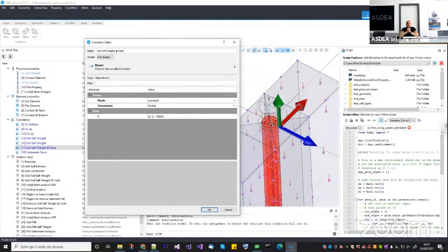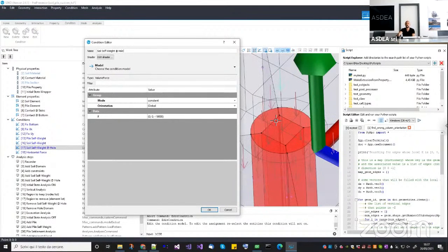So why do I need to do this? And here I'm referring to Dr. Benson. This is the reason why you had a crash in your program. The problem is that when you remove an element, and by the way, I'm going to remove these elements during the analysis, you also have to remove the floating nodes that remain here. If you remove elements and nodes from OpenSees, you have to make sure that you also remove nodal loads. Otherwise, when you do the analysis, there will be some nodal loads referencing a node that is not in the domain anymore. And OpenSees will simply crash.